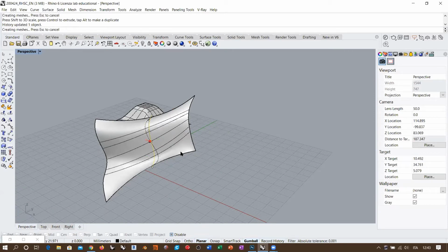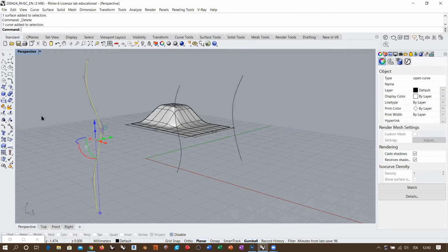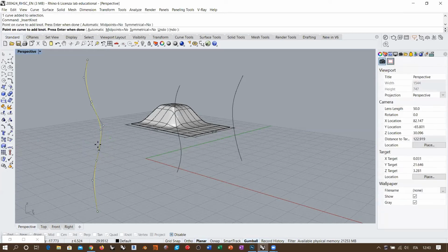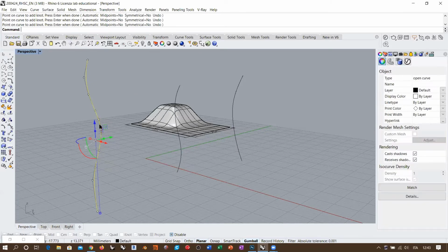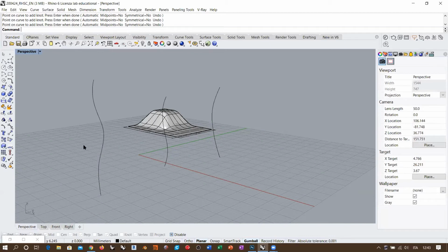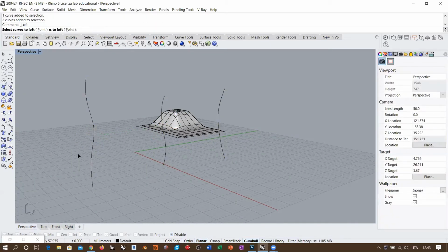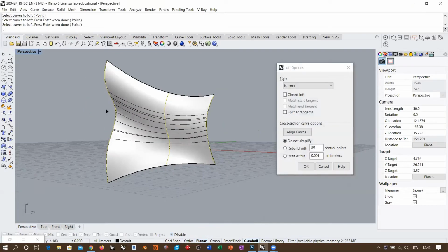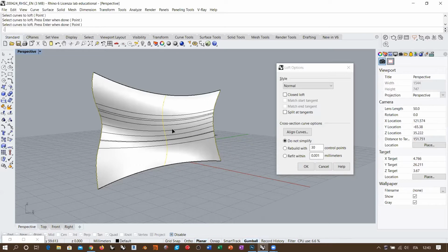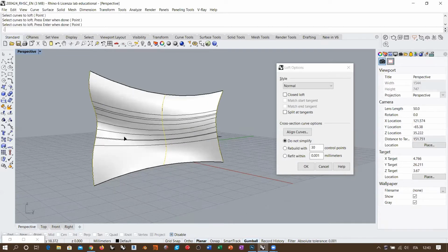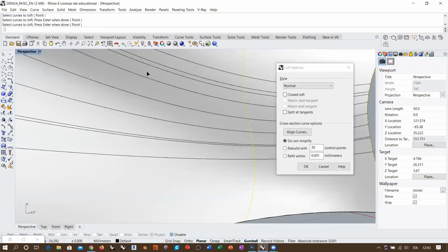Oh, by the way, what I want to do is also adjust or create some more complex topology by inserting knots along this curve, for example, in this area, okay, in the central area. So this topology is way more complex than these two here. So we know that if I execute the loft command like this, then I get more isocurves, more knot spans in this area, concentrated. Also, very concentrated knot spans like this and this one.